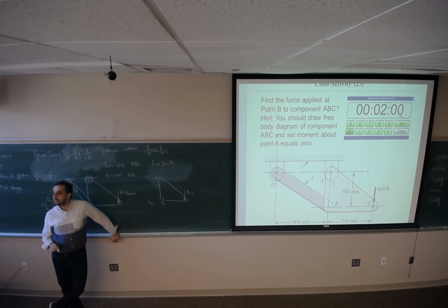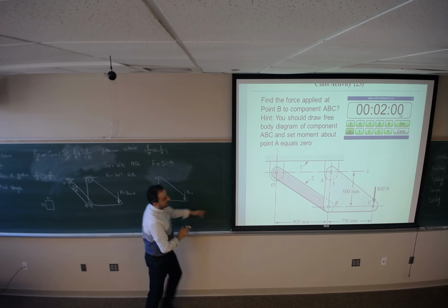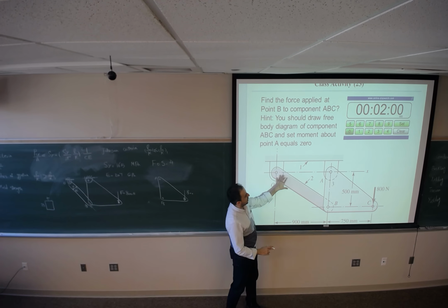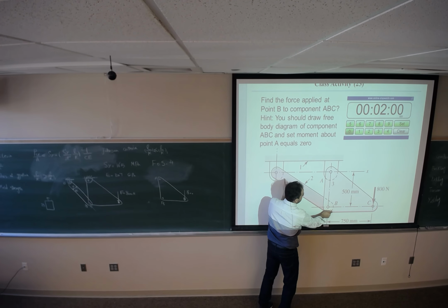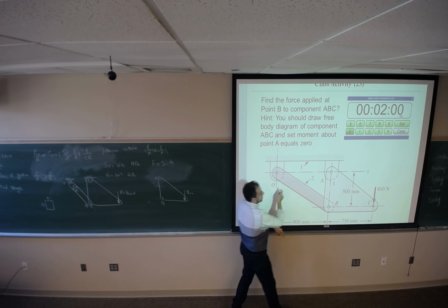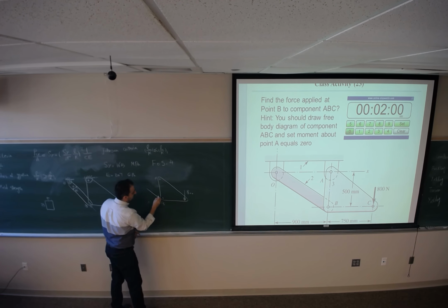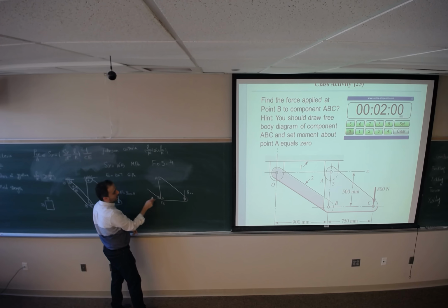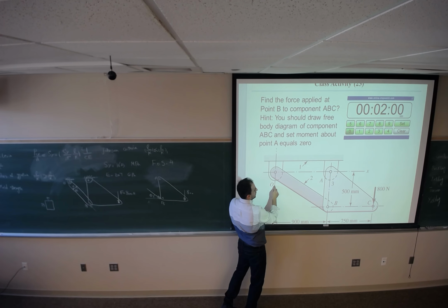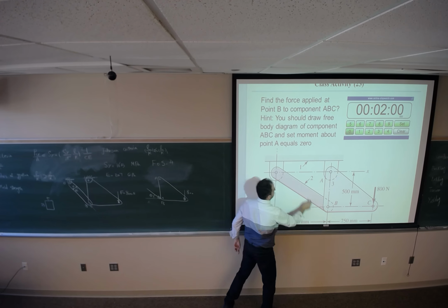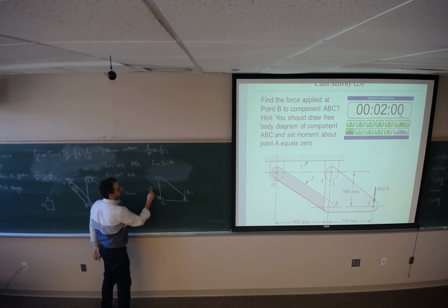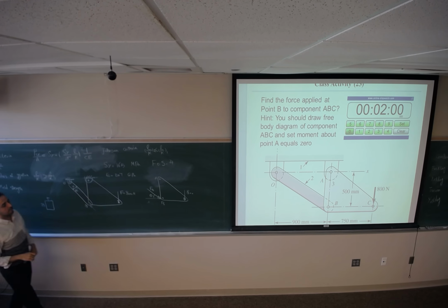Yeah. This bar, I mean, this system is not moving, so any force applied to this should be in the direction of this axis. So FB, either it goes up or down, should be in this direction with the angle of theta, which is equal to this. This angle should be equal to this. So this is FB. By knowing that, find the force applied to point P.